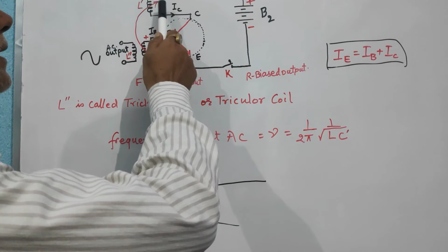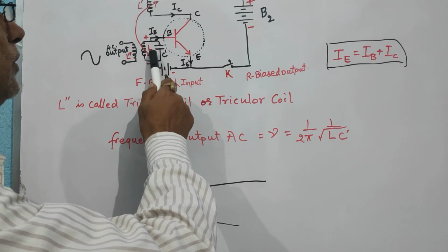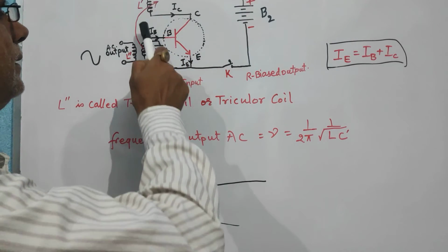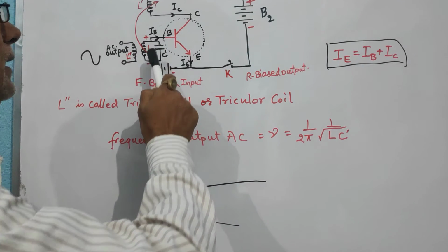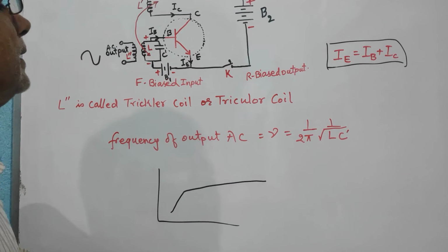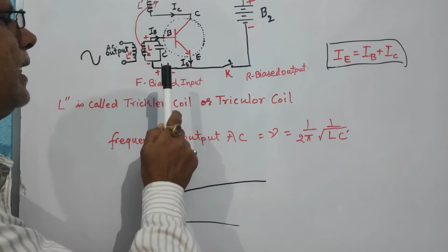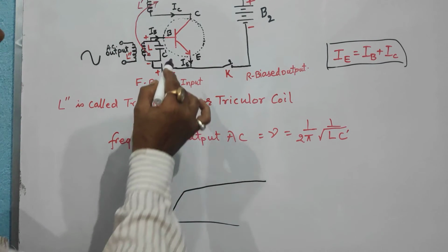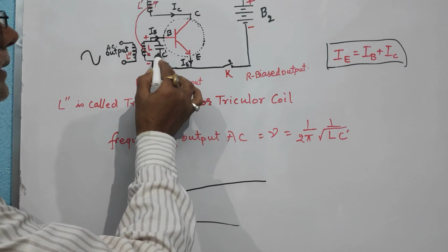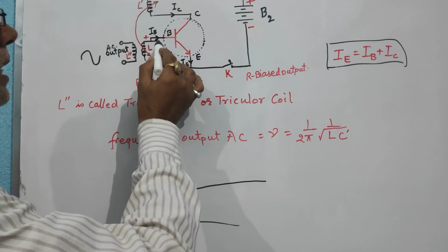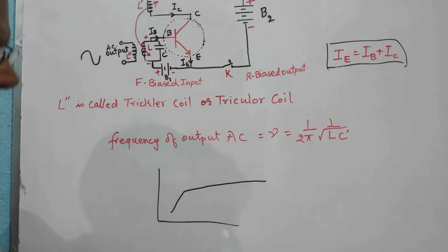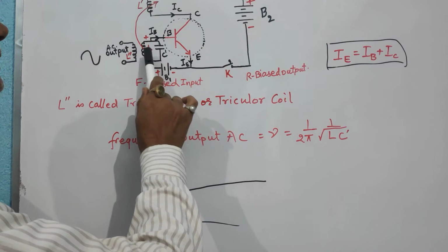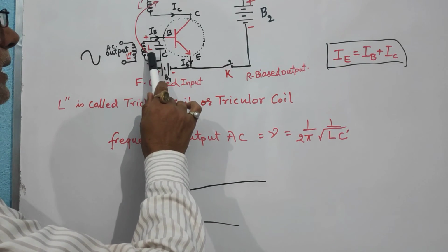and once there is no impact of mutual inductance between coil L dash and L, the back EMF produced across the L also vanishes. Once this happens, the capacitor C dash, which has now been charged in the reverse sense, meaning the bottom part of the capacitor is positively charged and the upper part is negatively charged, and now once the collector current becomes zero, there is no induced EMF across the coil L.